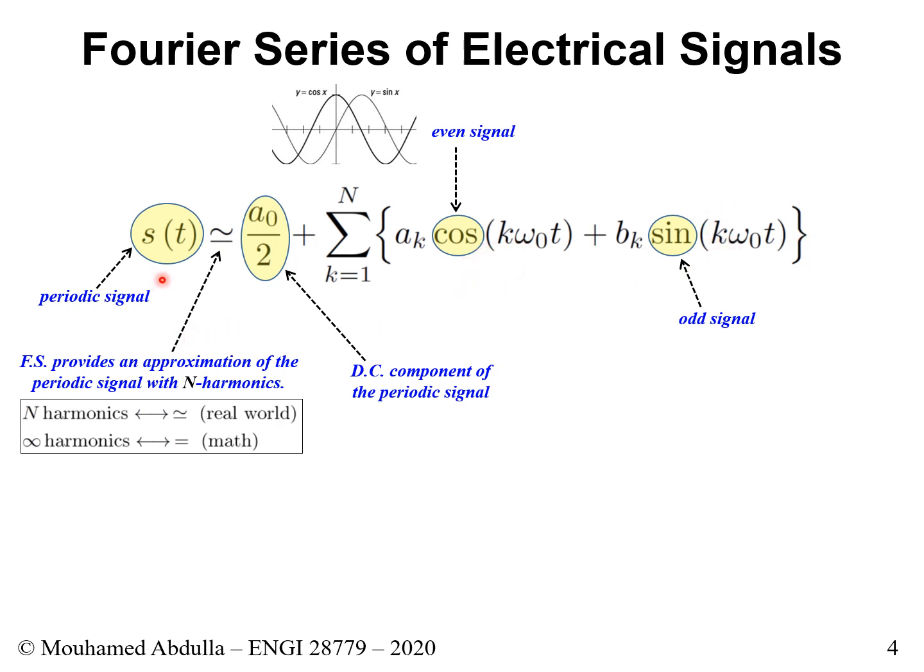So we said we take a periodic signal and we break it down into 2 sinusoidals. One that deals with the even component of a signal, and the one that deals with the odd component of the signal. So let's put it this way: if your periodic signal is an even signal, then right away what you end up doing is you only need to focus on this part here, right? And you will only need to find AK and A0.